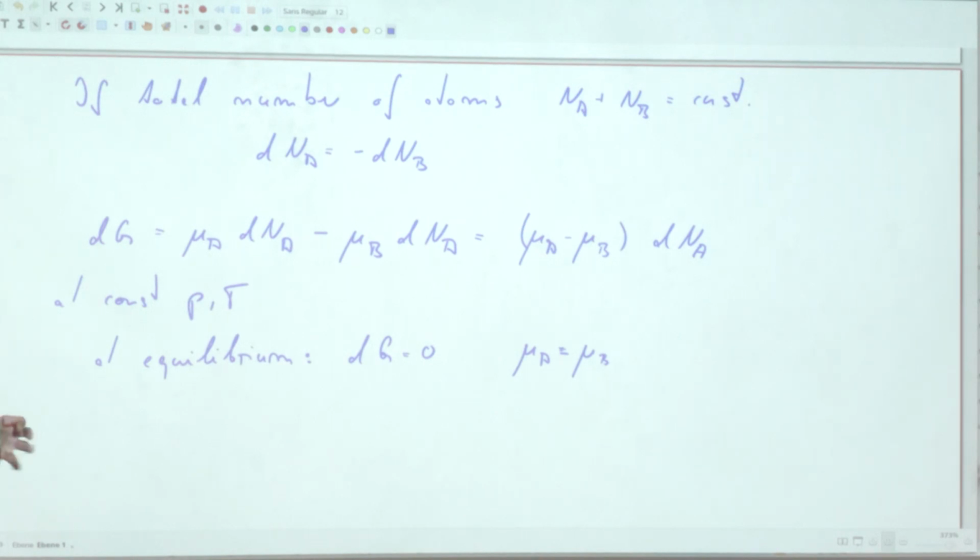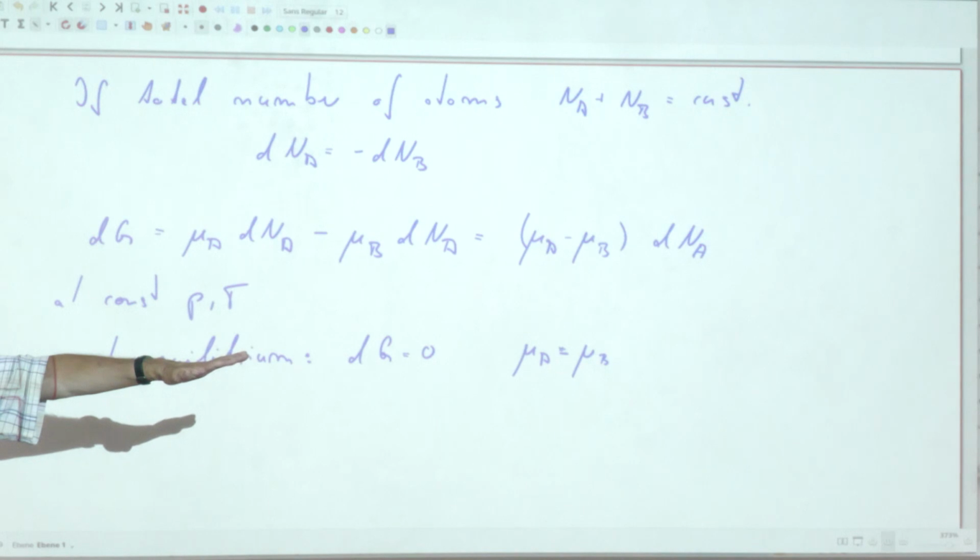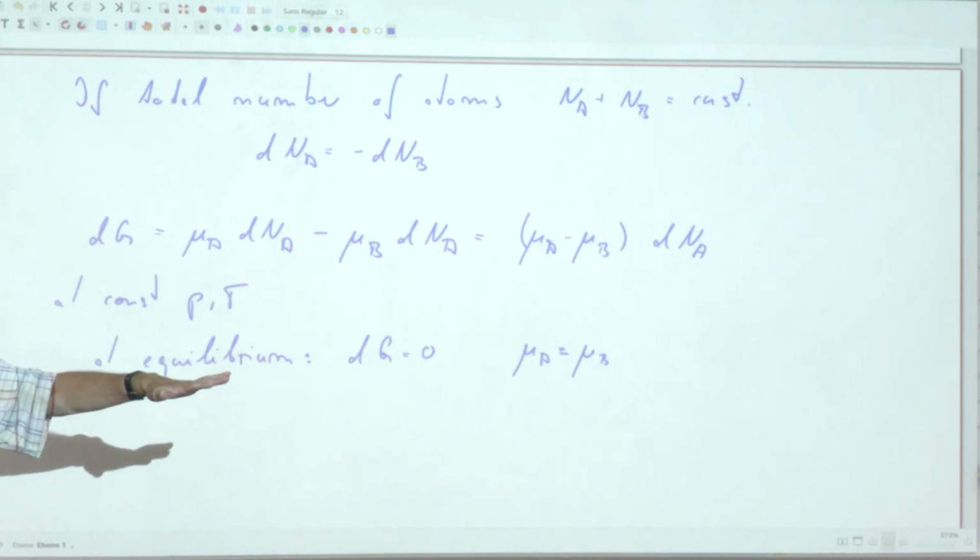So you take two pieces, a piece of copper with 10% of aluminum and a piece of copper with 5% of aluminum, then according to what you perhaps learned, aluminum will diffuse until you have 7.5% everywhere. But that's not necessarily true. Very often, for example if you form precipitates, diffusion does not go until everything is homogeneous and all concentrations are equal. But diffusion goes until chemical potentials are equal.